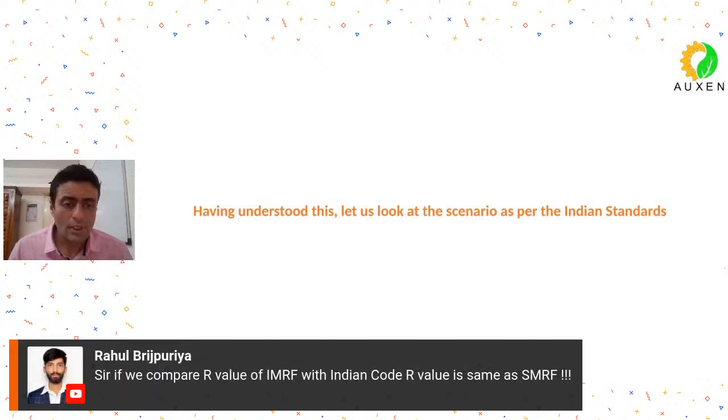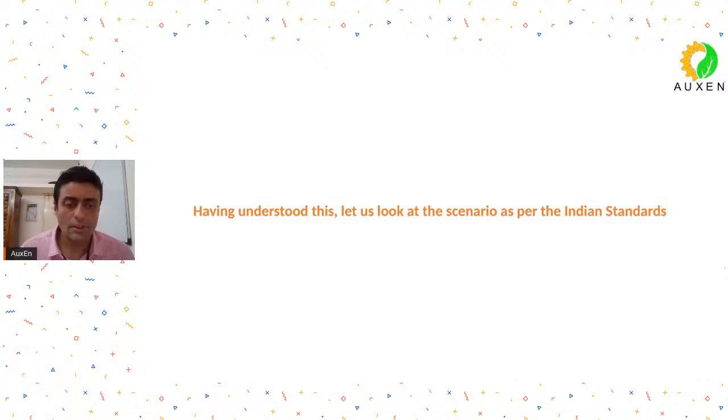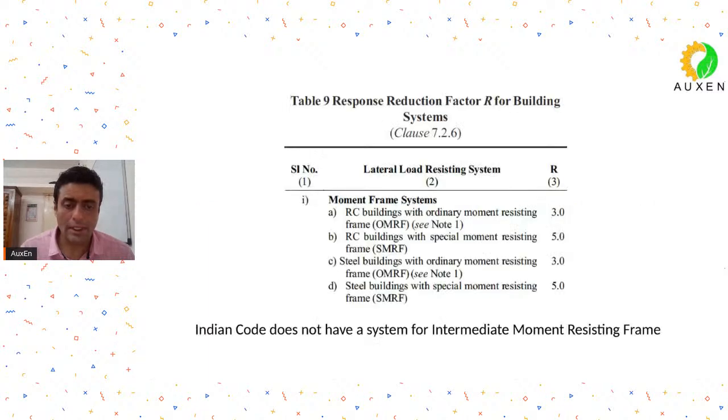Yes, very good. So, what is there in the Indian context? Who knows how flat slabs are dealt with in the Indian context, especially for lateral loads? Yes, anyone knows it? So, in the Indian context, flat slabs are taken to be a big villain. When there is an earthquake load, flat slab is the biggest villain in the eyes of the Indian standard, isn't it? So, you are basically not allowed to use flat slabs in the Indian context with earthquakes.